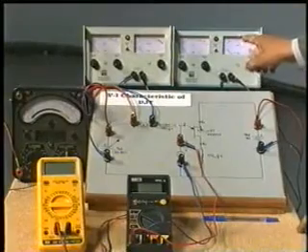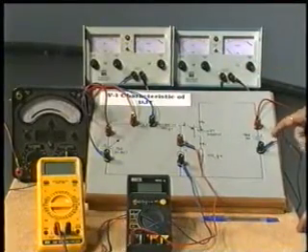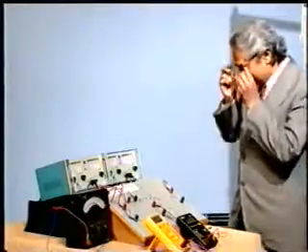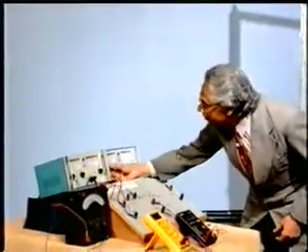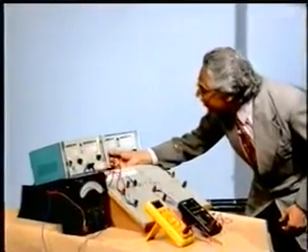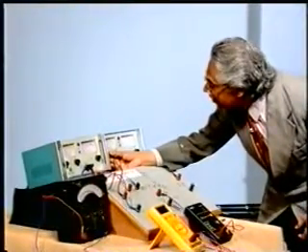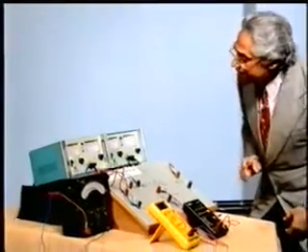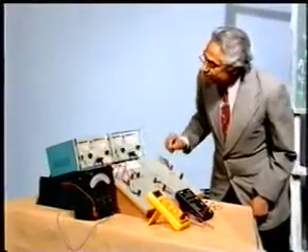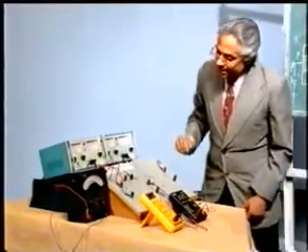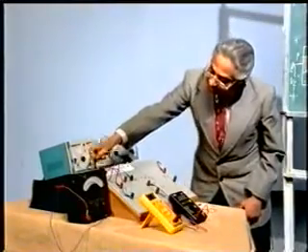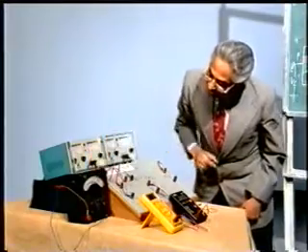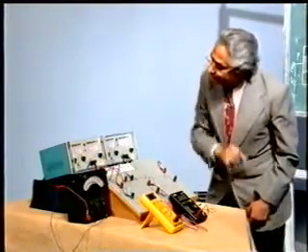And here in this power supply, as you remember, I have to give a constant 10 volts. So let me use my specs, it will help me, and I am going to fix a constant 10 volts here. Constant 10 volts is being given here, and here I have to just vary the voltage in steps, and I will look at this multimeter. Please concentrate on this multimeter. Whenever there is a conduction, it will show a shoot and that will indicate the triggering of the device.